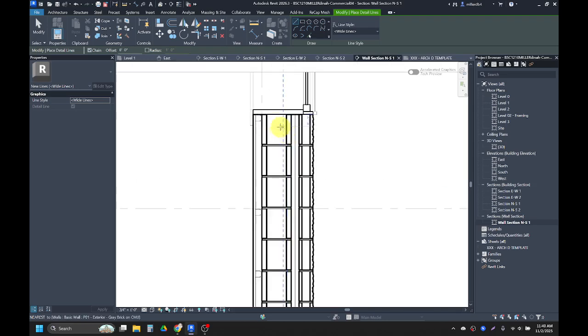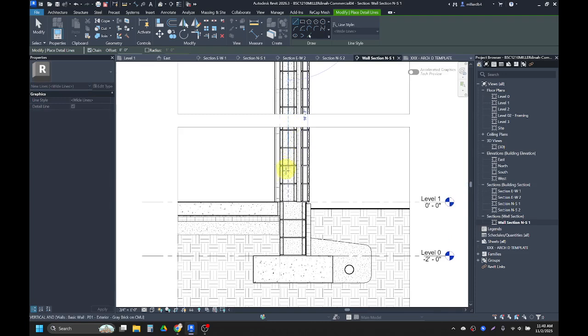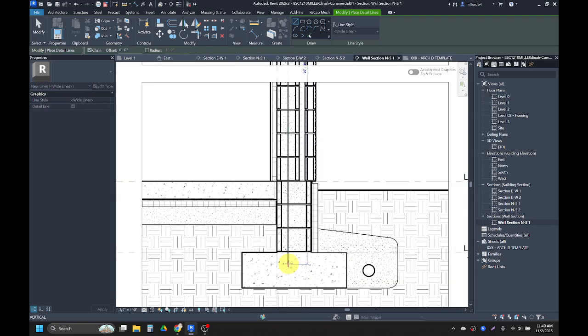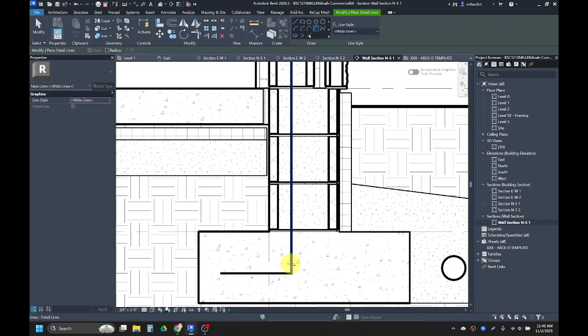And I'm going to start it centered underneath my window, and bring it all the way through to my foundation. And then I'm going to make a hook towards the left. And before I hit escape, I'm going to go into the fillet arc tool and click on these 2 lines. And I'll give it a fillet of about that much.